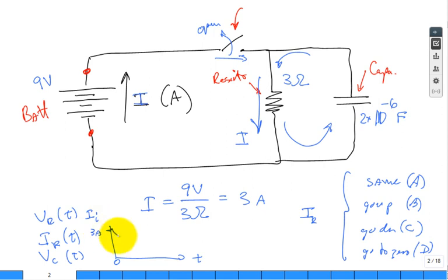What does it do? It's kind of just a boring function. What is the most boring function in engineering and science? The exponential function, isn't it? And so doesn't the current through the resistor as a function of time, isn't it the initial times e to the minus, and now you need to help me up here. I know that time is up there, e to the minus t for time, but something else, a constant, is up there. What do we call that? Isn't it RC? RC, the product of the resistance value in ohms and the capacitor's value in farads.